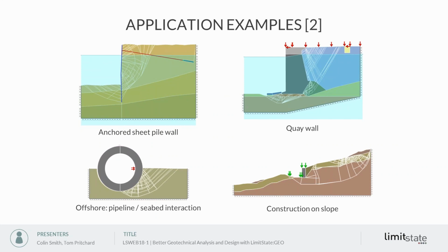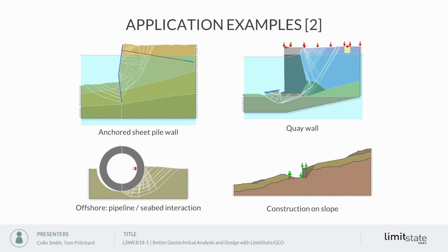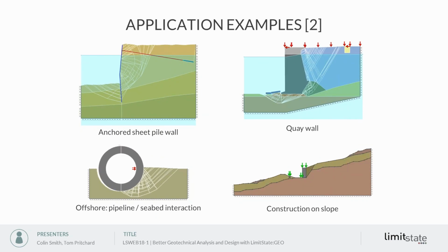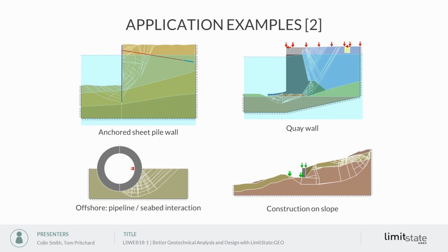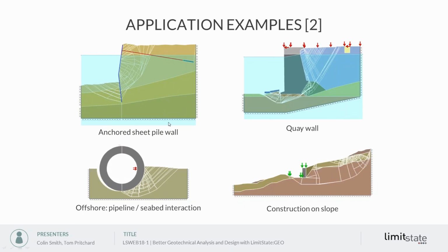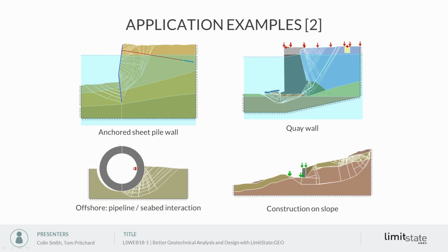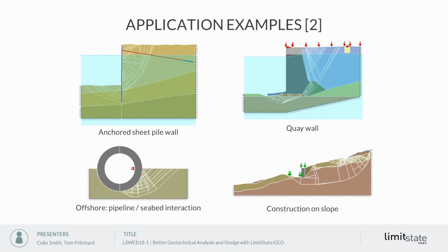So we have materials or objects in the software from which you can effectively define sheet pile walls or soil reinforcement or anchor tendons, and those can be modelled. And in the case of sheet pile walls, the software will model bending failure of the wall itself, and a range of other problems such as key wall, slope construction, offshore problems, have all been used. The software has been used to solve that full range of problems.